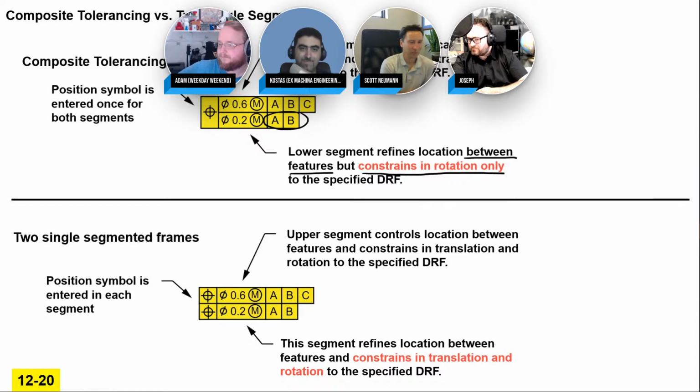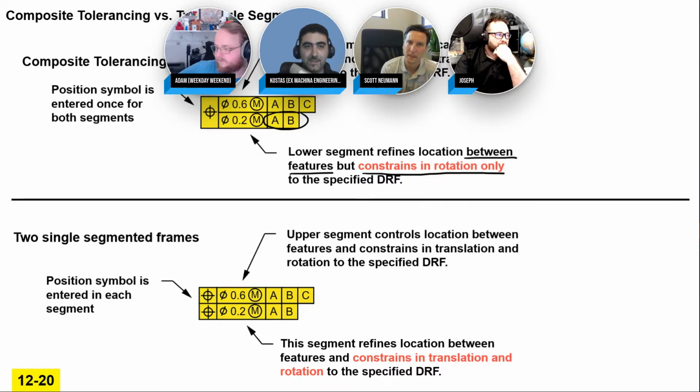That one would probably be a whole other hour to talk about. It's also different in ASME and ISO, which is why I didn't want to get into too much of the muddy water of the differences between ASME and ISO. But just to confuse everybody even further, if you look it up and understand why that happens, you will also understand why in most parametric CAD systems, you add constraints which feel natural and logical to you, and then the system tells you, I cannot do that because you just over-constrained your part.